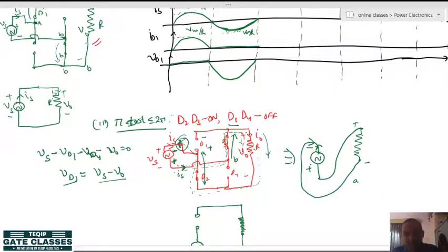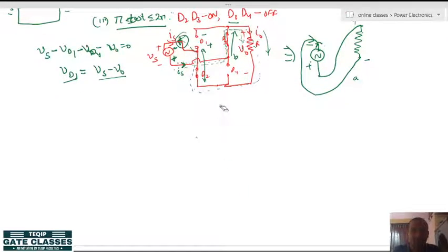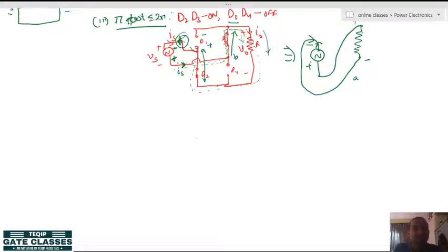Because you can see here that the load voltage is something flowing from here. Or in another way you can understand it in an even simpler way. Let us remove all this. Here you can see that since this is short circuited, if you draw the circuit, because of this short circuiting, this point will come here, and this point is already here. So this plus is coming here and this minus is already here. So, you can see that the diode voltage is parallel with this supply voltage.